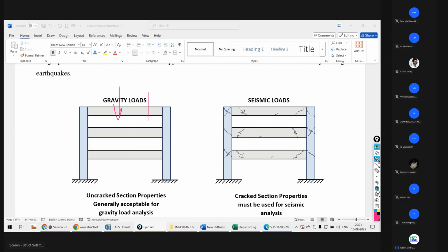So what we can do, we can find out the stresses, we can assume the full strength of the section throughout the life of the structure. पूरी life में under the serviceability case, under the factored case, we can consider that our full section with its full strength is ready to resist your load. जो भी आपका लोड आ रहा है उसको रेजिस्ट करने के लिए पूरा सेक्शन फुल स्टेबिलिटी के साथ अवेलेबल है for resisting the load.